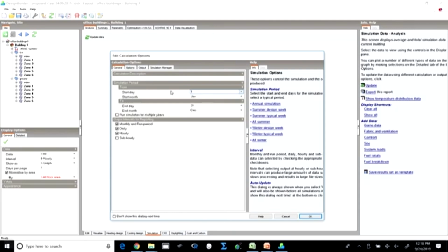For example, the U value of the wall can be compromised with because the U value of the roof has been reduced substantially even beyond the ECBC prescription. So, whether those changes in parameters can be brought in, that is what the whole building simulation facilitates us. So, we will stop with this lecture today, and tomorrow we will continue to analyze the results.